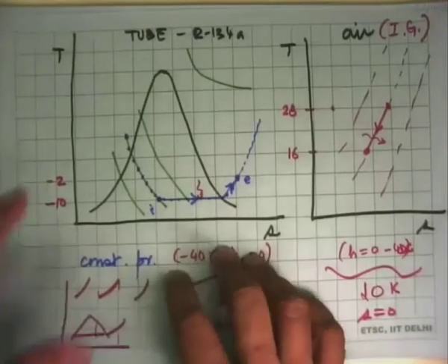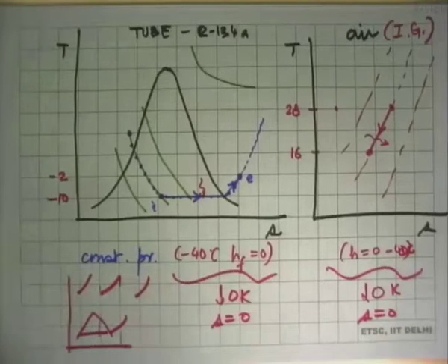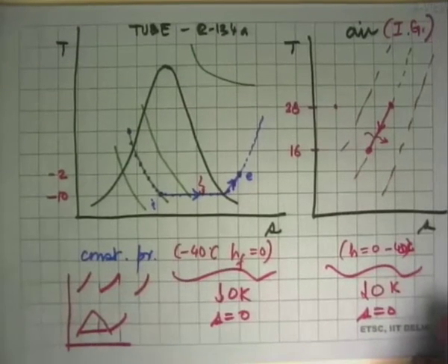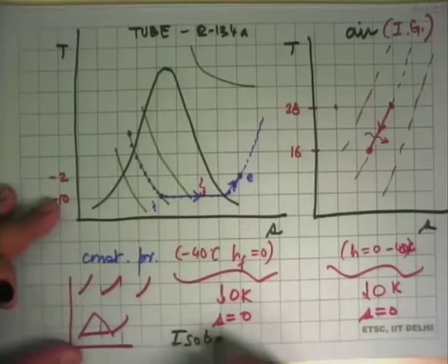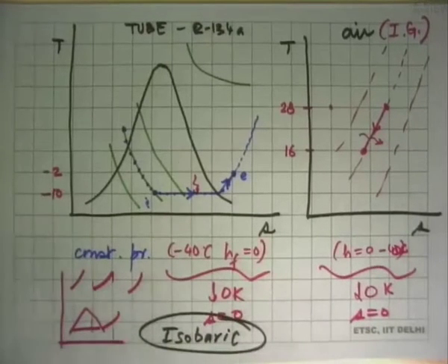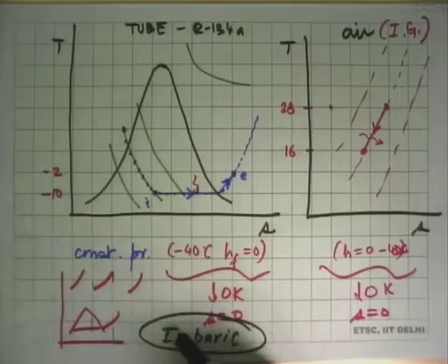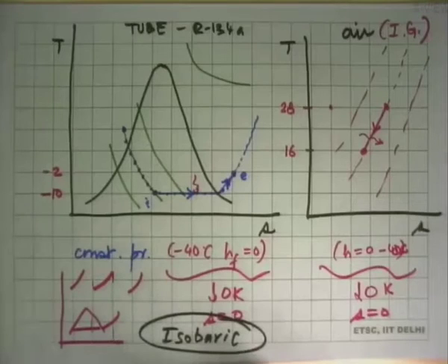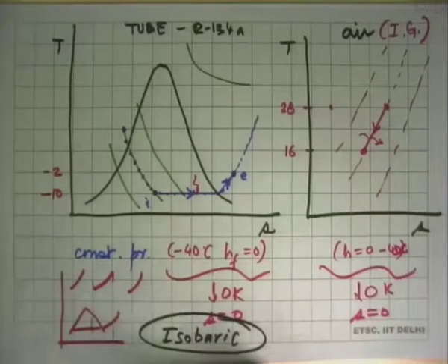Okay, so the main assumption that has come out of this is that in addition to all the assumptions that we do, heat transfer processes either through heating or through cooling, we take this to be isobaric processes. That's the additional thing that has come out. And the reason is that these are substances going through a device. We are neither doing work on them, we are neither doing great expansion on it, and so the pressure in the first analysis is assumed to be constant.